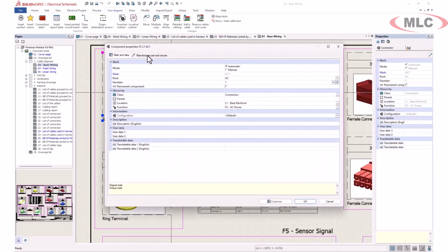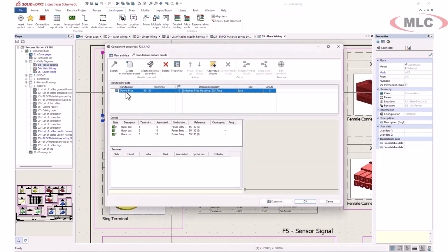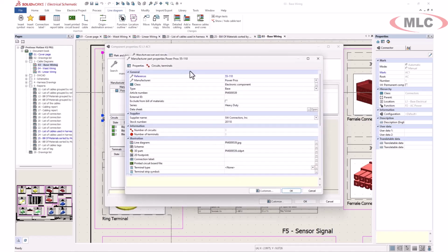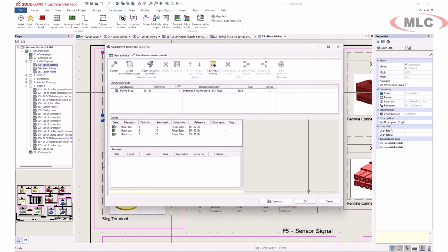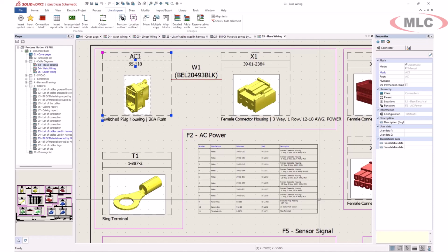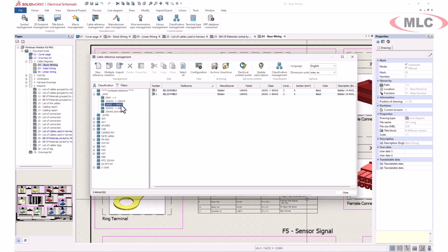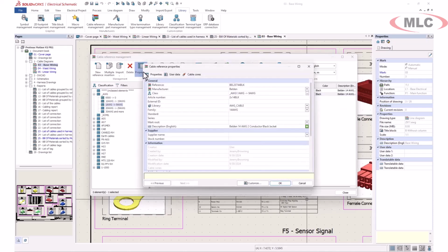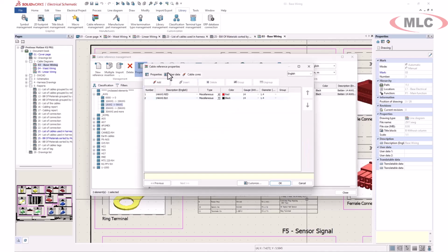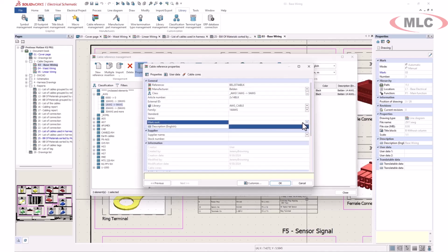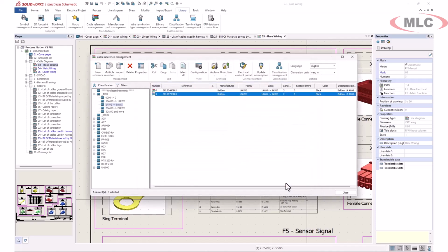Like I mentioned, Excel import extends to cables as well, and I can define them completely with cable cores. We need a lot of cables for this machine, so good thing cable management and configuration is enhanced for a better user experience. First, the Mark Route parameter is added in the Properties tab. When you add this cable to a project from now on, it will be PWR.